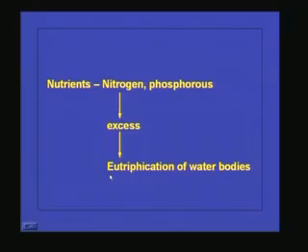But in a separate system, the carbonaceous oxygen requirement is taken care of in one tank and the nitrogenous oxygen demand is taken care of in another tank. So, in the second tank only nitrifiers will be present, and whatever little oxygen is available will be sufficient for nitrification. So, depending upon the system, the oxygen requirement will vary.